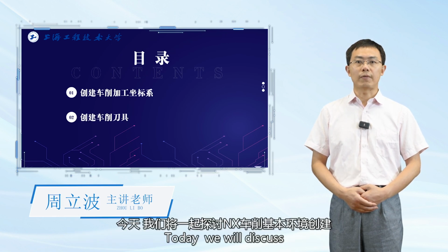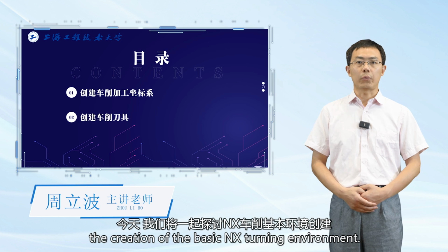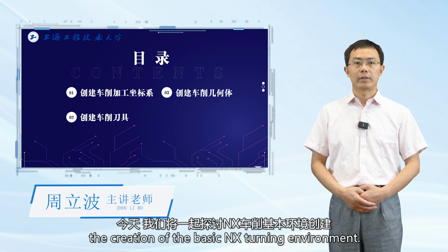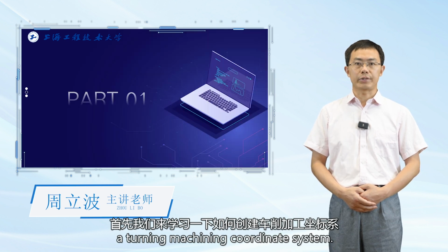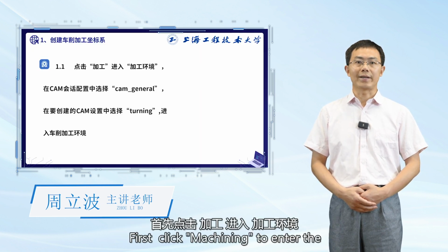Today, we will discuss the creation of the basic NX turning environment. First, let's learn how to create a turning machining coordinate system. First, click Machining to enter the machining environment.